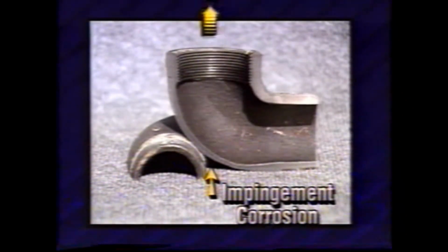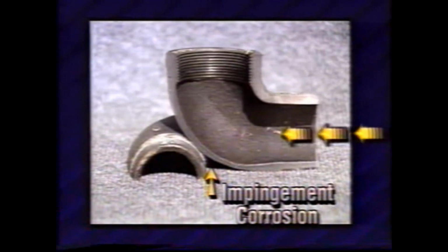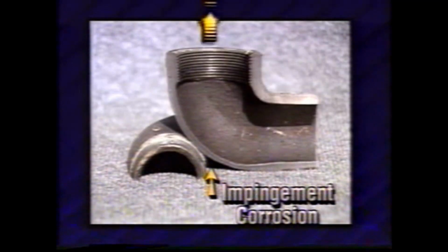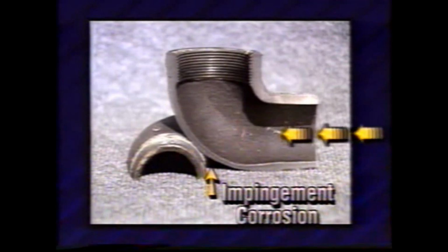Impingement corrosion is a severe form of erosion corrosion. An impinging high-velocity stream of water can perforate tube walls rapidly. Sand, silt, or mud in the water will erode tubes severely. Most often, impingement corrosion is found in the elbows and turns of tubes or pipes. It generally manifests itself as deep, clean, horseshoe-shaped pits with deep undercut ends pointed in the direction of fluid flow. Impingement corrosion attack can also occur as the result of partial blockage of a tube, deflecting the main flow against the wall.